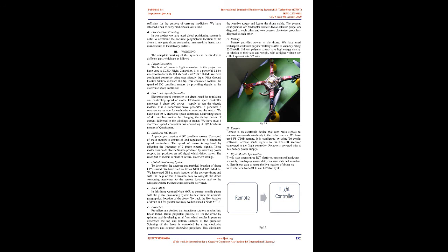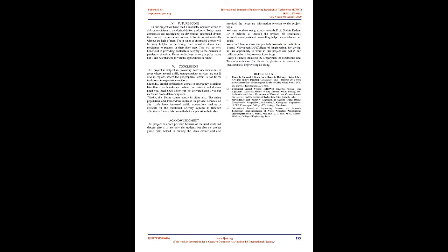F. Propeller. Propellers are devices that transform rotatory motion into linear thrust. Drone propellers provide lift for the drone by spinning and developing an airflow, which results in a pressure difference between the top and bottom surfaces of the propeller. Spinning of the drone is controlled by using clockwise propellers and counterclockwise propellers. This eliminates the reactive torque and keeps the drone stable.